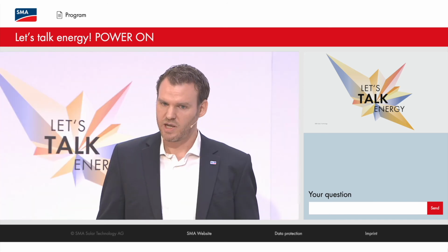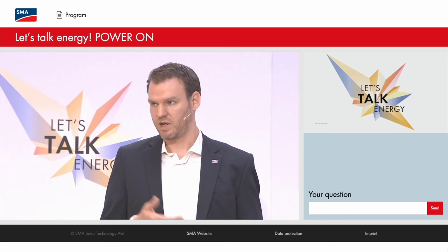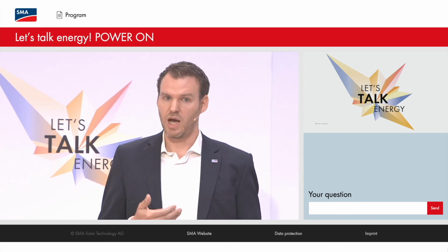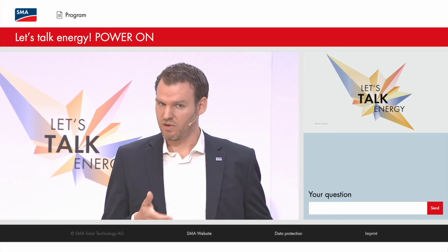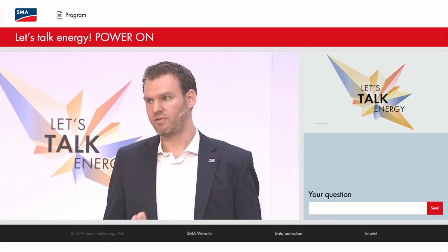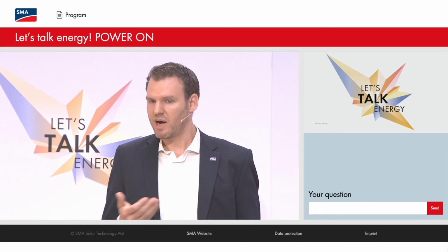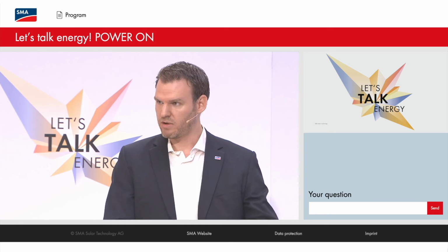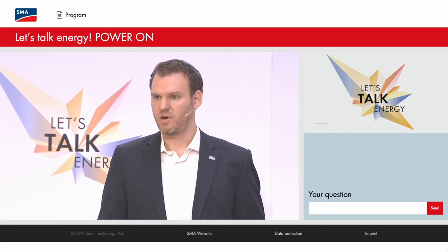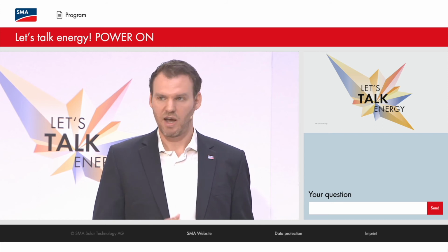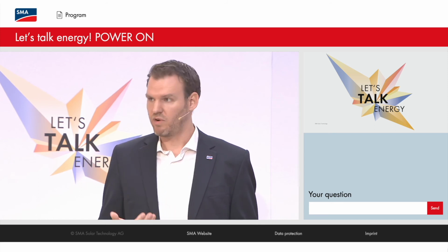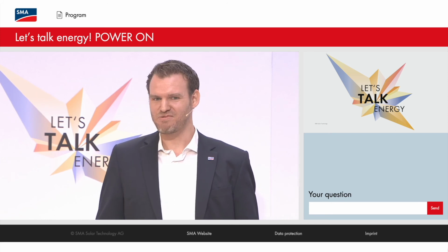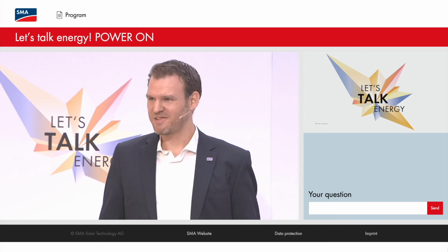Okay, how many inverters is that actually, and how much solar should I connect with regards to DC oversizing? In many cases, you have to start a grid study pretty upfront. Depending on the market, sometimes the project developer is doing it, and not the EPC. And in other markets, you actually start with the land because you have limited space, so you start adding the panels that fit to the land, and then you add inverters, and then you basically apply for the grid connection with the number of inverters you have. So there is no standardized procedure, and there is no simple answer. There's not the ideal project. Maybe the ideal architecture, but not the ideal project.